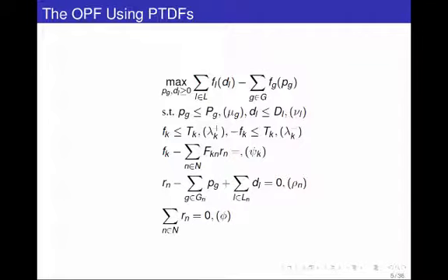So the conservation of energy constraint says that if on net I'm injecting 3 megawatts here, then on net I have to be consuming 3 megawatts here. So when I add up the net injections from all buses in the network, including the hub, then the total,